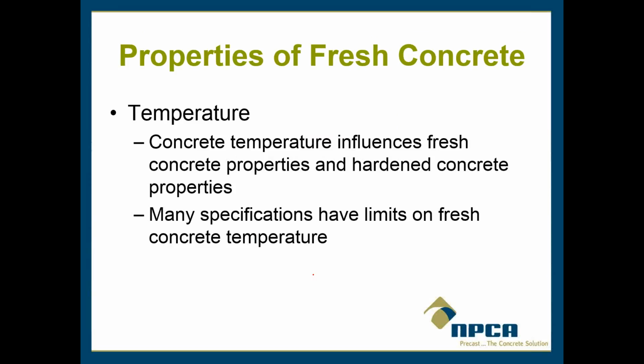Okay, temperature tests. This seems like a really minor thing to test for, and it's probably, hopefully, the easiest one to do. But it's actually extremely important, because if the concrete is too cold, for example, if it freezes before it reaches only 500 psi, then you have to toss it out. You have to discard it. It greatly affects the concrete's ability to develop strength, and it stunts the crystal growth that we'll talk about later. So it really, really impacts the concrete in a negative way if it's too cold.